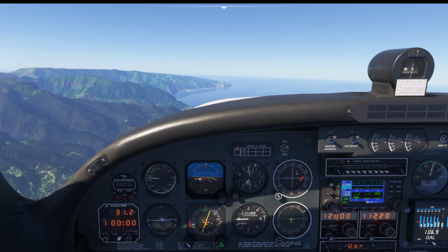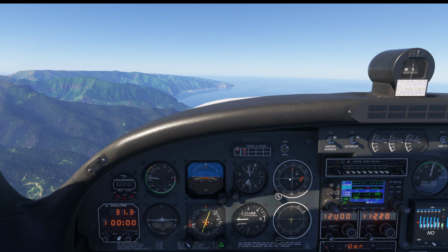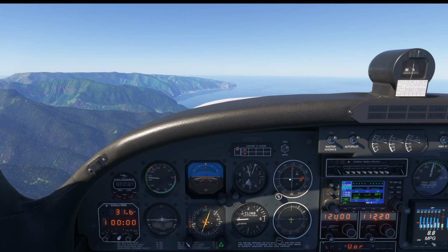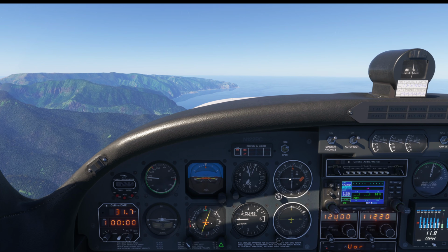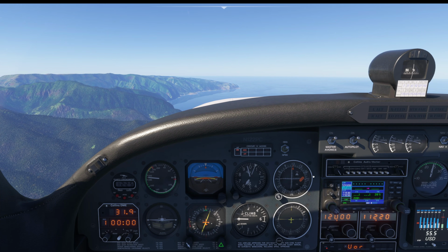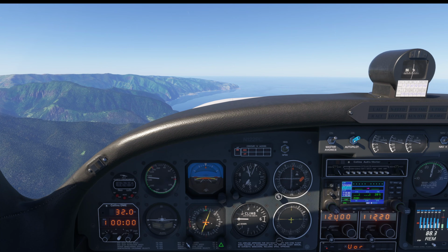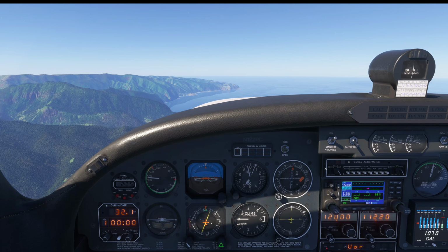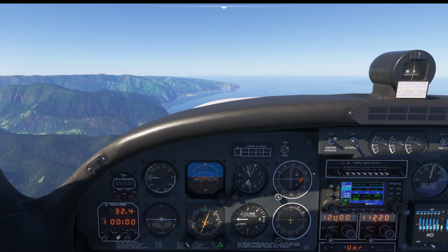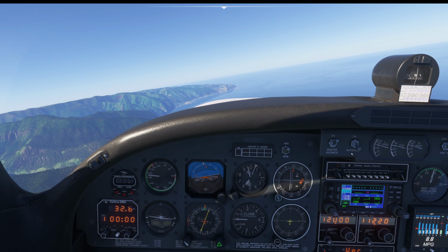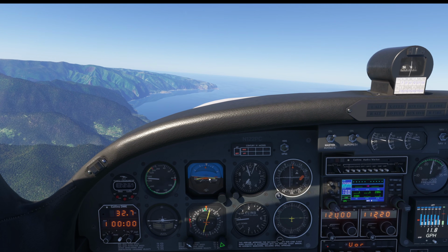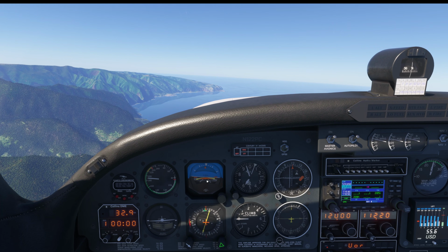In other words, the master switch works pretty much like a flight director switch in bigger aircraft, for example Boeing 737. There is no warm-up or self-test period. The autopilot is ready to work at the moment you turn the master on. My advice is do not do that until you want to use the autopilot or follow the flight director. And when you engage the autopilot, verify that the flight director is centered, or at least points in the direction that you want to fly.